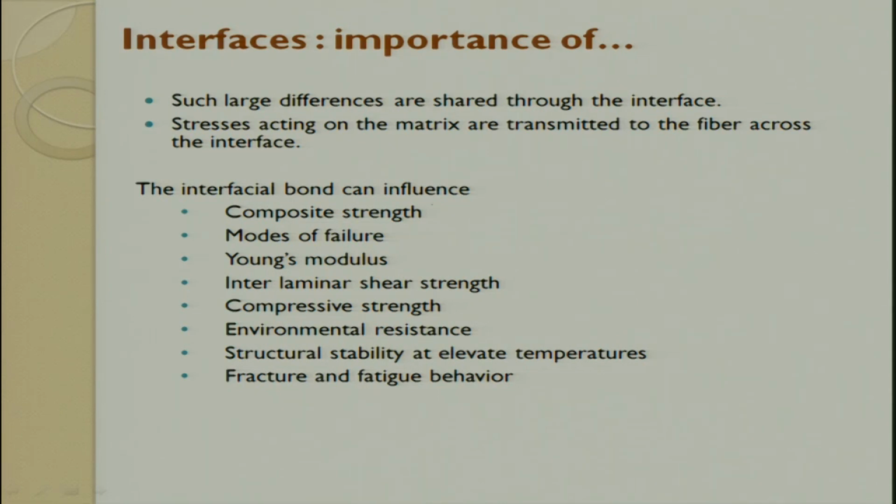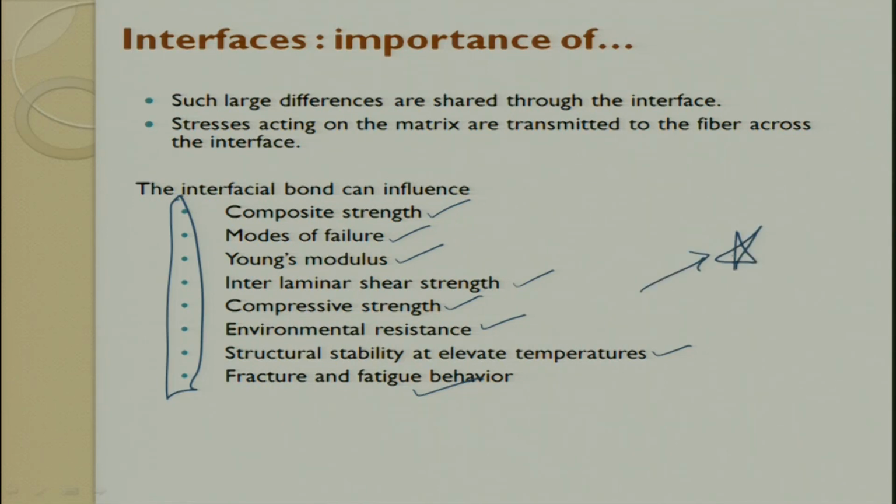So, the interface can influence the composite strength, modes of failure, Young's modulus, interlaminar shear stress, compressive strength, environmental resistance, sustainability at higher temperatures, and fracture and fatigue behavior. These are all important properties for the interface, very, very important for the interface in ceramic matrix composites.